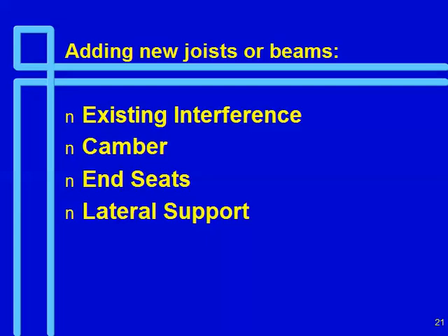So the last thing you want is a joist with a big hump in the middle that you can't stuff into the supports. Okay? So you can order a joist with no camber. If you don't do that, you're going to get a joist with camber. They all camber them. It says it's optional in the K-Series spec, but I don't know of a single joist manufacturer that does not provide camber. So think about the camber.